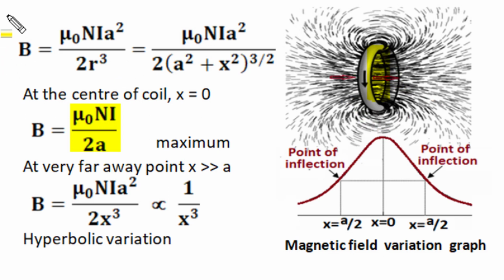Now mathematical analysis of this relation indicates that for small values of x, the decrease of axial magnetic flux density of the current carrying coil is small, but as we increase axial distance to both sides of this coil from the coil plane, the rate of decrease of magnetic flux density with axial distance increases. This rate of change becomes maximum and constant at an axial distance equal to half of the radius, and then again its